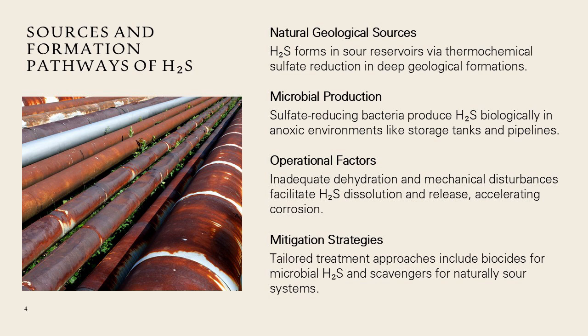For example, systems dominated by microbial H₂S production often require biocide supplementation in addition to scavenger chemicals. Conversely, naturally sour systems may require continuous scavenger injection to manage gas phase concentrations. A comprehensive analysis of sources enables engineers to tailor strategies that optimize treatment effectiveness and enhance asset longevity.